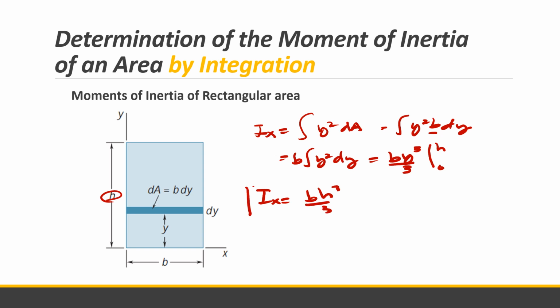So this is the moment of inertia of a rectangle. So this is fixed na yan, no? So as long as it is a rectangle, ito yung magiging moment of inertia niya, b h cubed over 12 or 1/3 b h cubed. So that is the moment of inertia. So yun lang. So you just evaluate the integral, get the moment of inertia, and this is always positive.